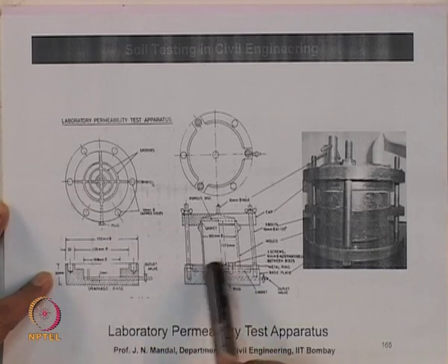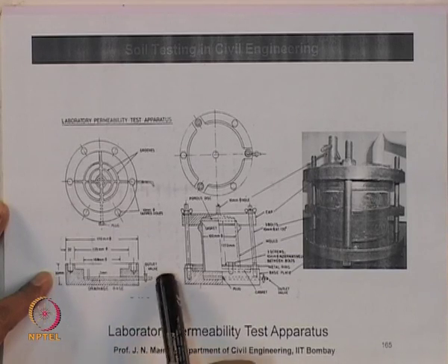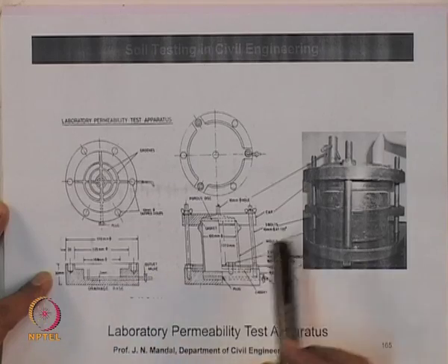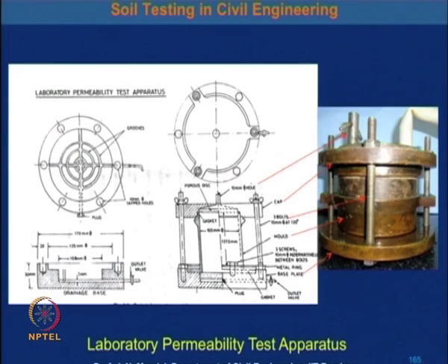All this drainage base is also given here, and this is the outlet valve. So, from this equipment we determine the coefficient of permeability.